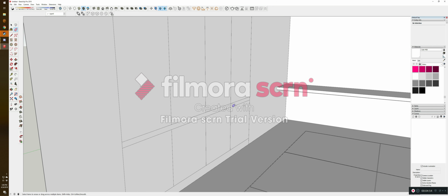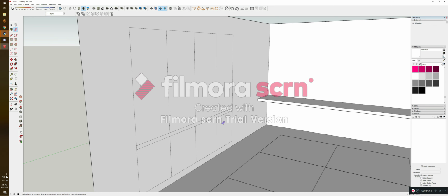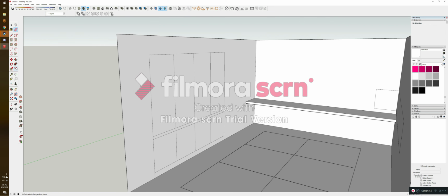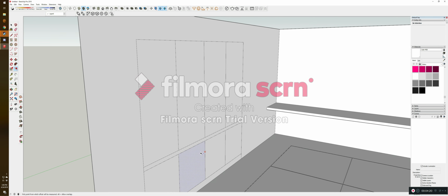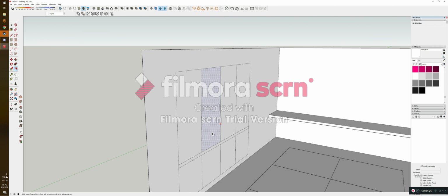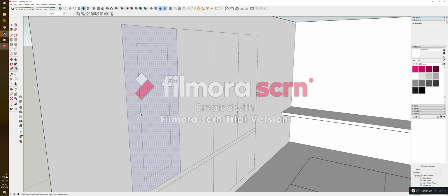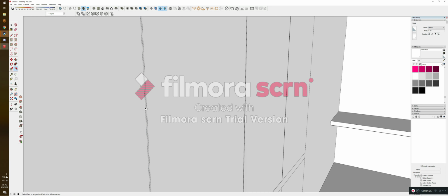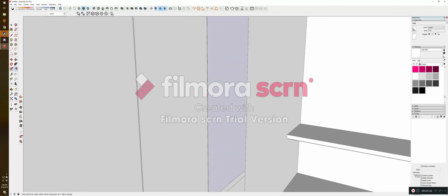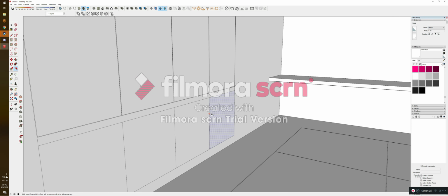Okay. And again, I'm going to be offsetting each of these squares just because they're going to be a glossy material. And once you get into V-ray, V-ray doesn't recognize single lines. There must be a gap in between tiles if you want the tiles to distinguish themselves from one another.